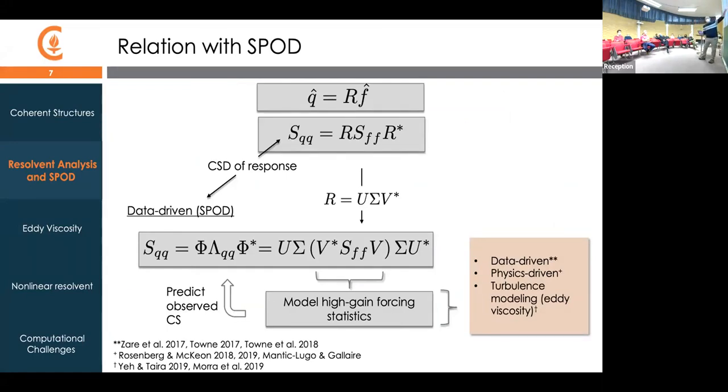No, the decomposition is taking the linear operator, right? So the linearized Navier-Stokes. The resolvent modes are the decomposition of the operator. In the case of CFD, that's a matrix, but in general, that would be an operator, and this is the SVD of that operator. So it's a linear operator, and the SVD gives you a relationship between forcing on the right-hand side and the response.